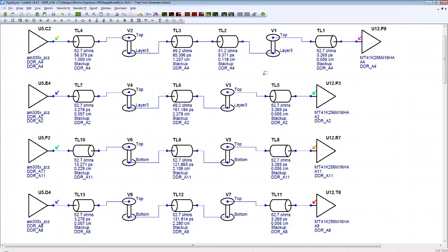So again, in previous statements we said our expectation is, because of the very nicely matched address bus, we have only a picosecond of skew. Now let's do a simulation. I downloaded, as I said, IBIS simulation models for the Sitara processor as well as for the Micron DDR3 low power memories.